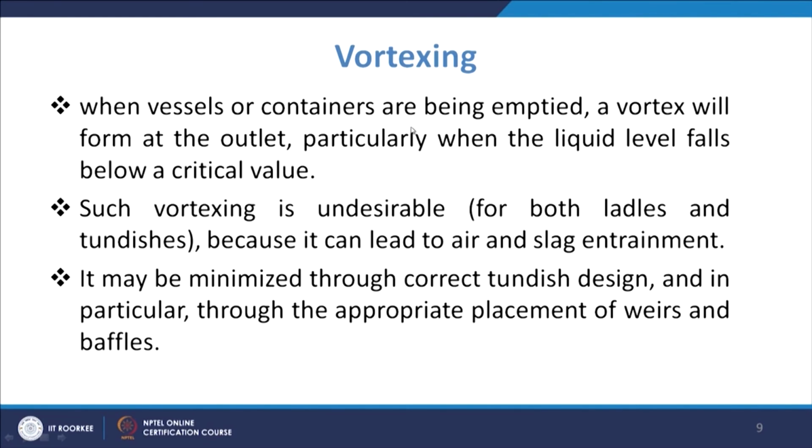You must have appropriate placement of these weirs and baffles. That basically helps in ensuring that there is no vortexing in the Tundish. So, that is another part which has to be taken care of while we see what should be those mechanisms by which you can avoid these vortexing.